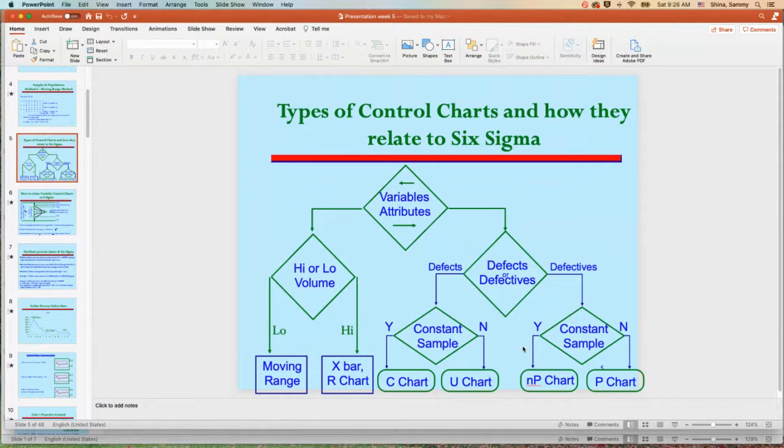So for instance, if your reject rate is 2% historically, your sample size will have to be 100. If your reject rate is 1 in 10,000, a sample of 10,000 is impractical. Might as well just go to 100% inspection.